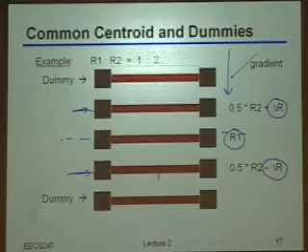More restrictive design rules? Okay, you said there are more restricted design rules. That's also potentially true as well. But I think the answer is actually a little bit simpler in the following sense. All of this scaling was about improving the density, right? So if you think about it, we're packing 30, 100, 1,000, even 100,000 times more transistors in the same physical space as we used to. If I really had very large gradients across the same physical area as I used to have, then pretty much guaranteed nothing would work, right? So indeed, the fabrication technology has gotten a lot better at controlling those gradients.